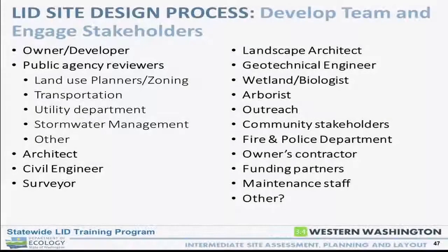An architect, if you're doing that kind of project, surveyors, any conventional project, geotechnical engineers, and I'm going to add on to that hydrogeologists. It's not just the geotechnical considerations in terms of foundation support and wall design and all of that, but it's where the water's at and where water may go if you infiltrate. It's a very key consideration of the project, and engage them early in the project so you understand their scope for developing that design criteria for how you're going to model the performance of these practices, but also understanding the risks. And they can map out where and when LID or infiltration specifically is appropriate.